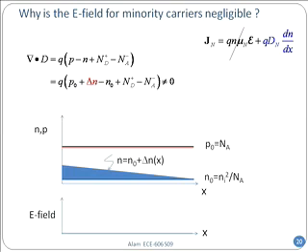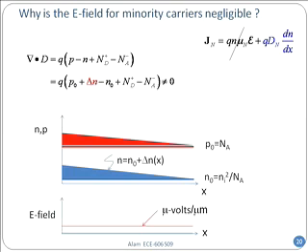So as a result, it will increase the electric field a little bit in that region, a very tiny amount, and it will pull in holes from the contacts to almost exactly compensate the electron concentration. So it's not photo-generated. It is coming in because it wants to minimize that quantity on the right-hand side. So it will pull in a little bit of holes to match the profile.